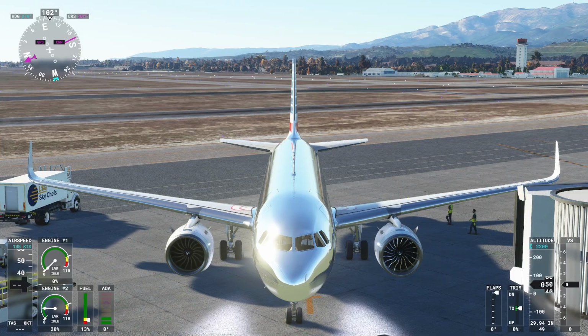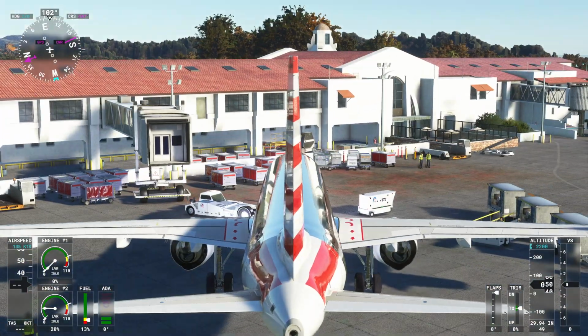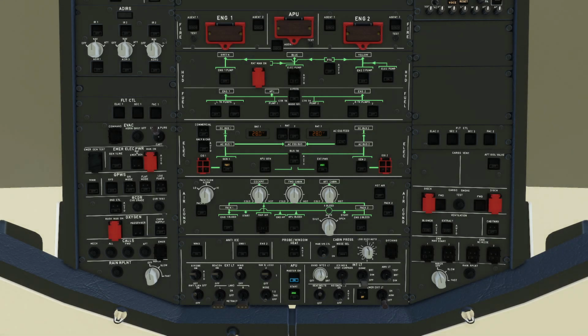So when I turn off engine 2, if the APU was not on, then all of the power in the aircraft was shut off, and you don't want that. So when you come into land, one of the pre-checklist items on the checklist is to turn on the APU and start it, right? That's what I did. So if I were to turn off engine 2, the aircraft will still remain on. I mean, the power, but the engines will shut off.